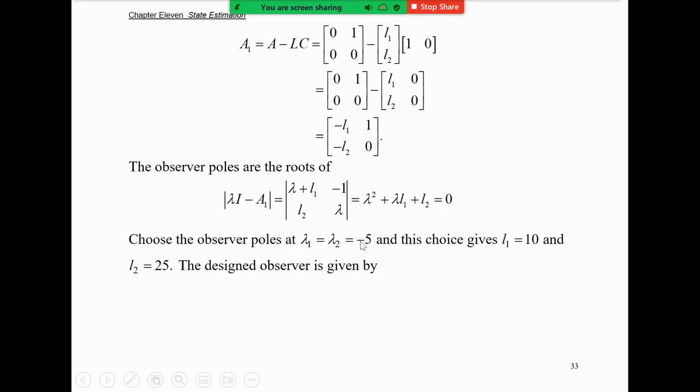Let's say you place the poles of the observer somewhere. If I give you the poles, you just place the poles at those positions. In your mini project, you design the poles to be 3 to 5 times faster. Of course, in some problems, if you are not given the poles, you design stable poles by yourself. You choose some simple numbers. But always remember, you have to give me stable poles when you do the pole placement problem.